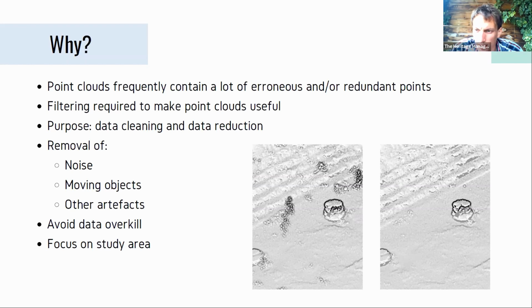I was not involved in the data acquisition of this point cloud. It's the point cloud of Eleusis in Elefsina, but most probably this cloud that you see here is a moving object, a person walking while the scanner was scanning its environment. And these are obviously points that have to be removed.